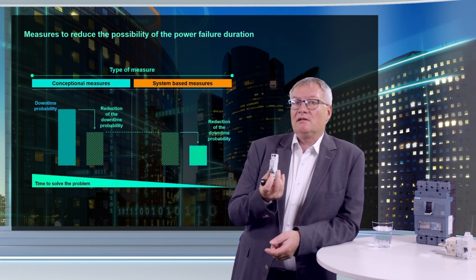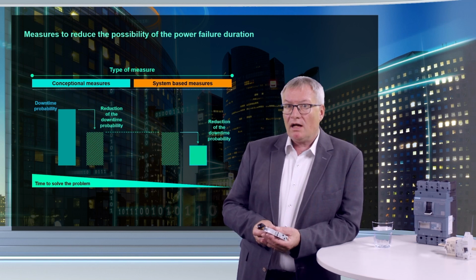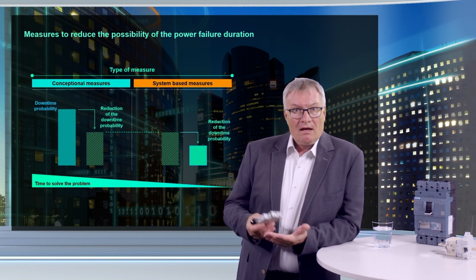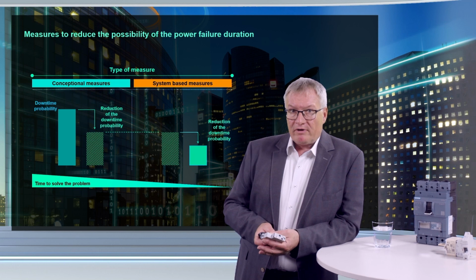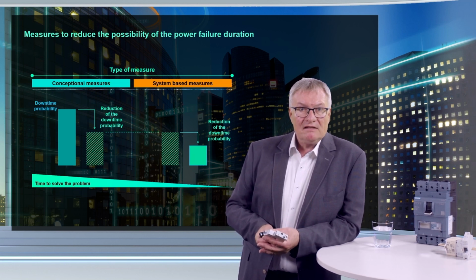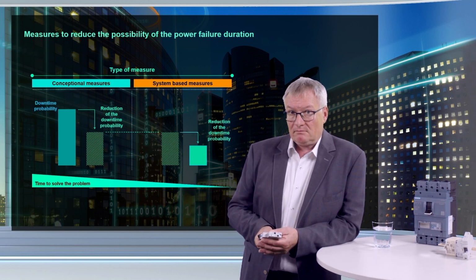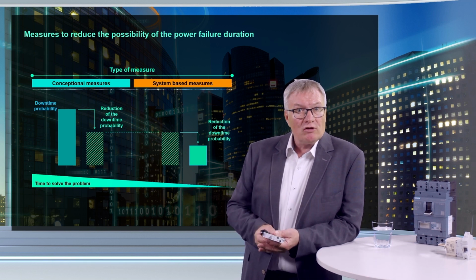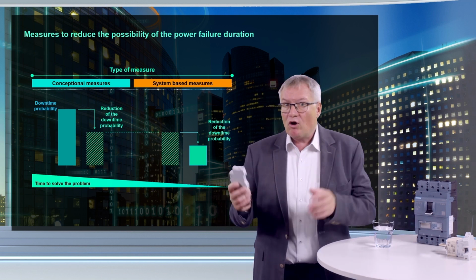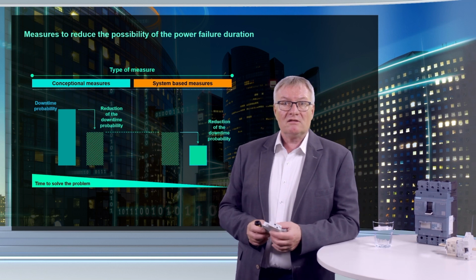They continuously collect operating data and provide warning or alarm messages in the event of a critical change. An identified change in operating data reduces the probability of failures if the message is interpreted correctly in a timely manner. With the implementation of a condition-based service, unnecessary time or load-based maintenance cycles, besides additional costs, can be avoided.